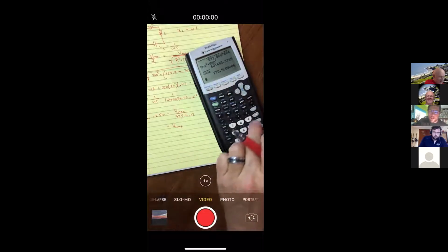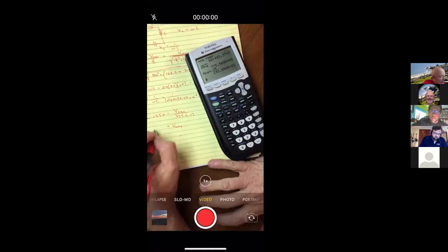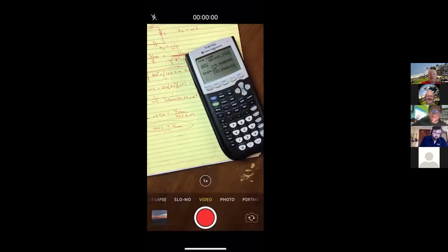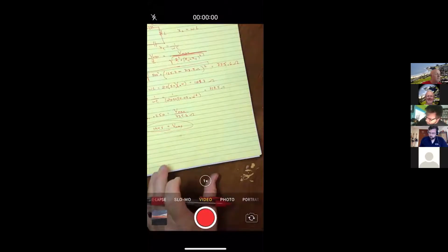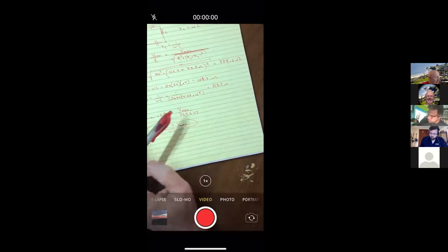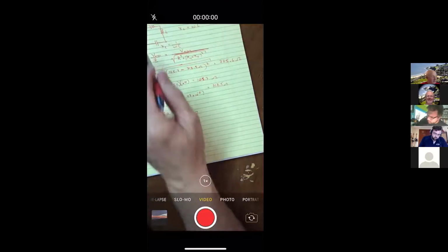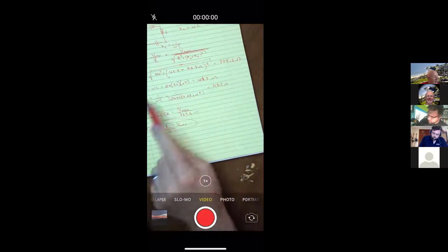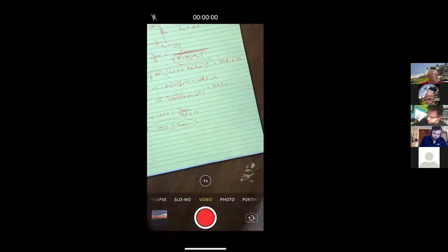All right, so I'm going to take that number and multiply by 0.25 and get 194 volts. So I would say that for part A, where it says what is the peak voltage, there it is. I would need 194 peak voltage as an AC source in order to get this much peak current or maximum current of 0.25.